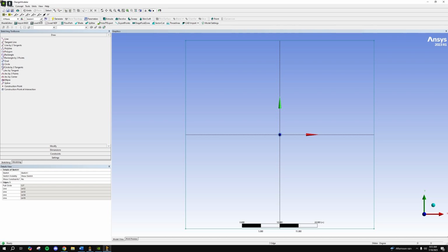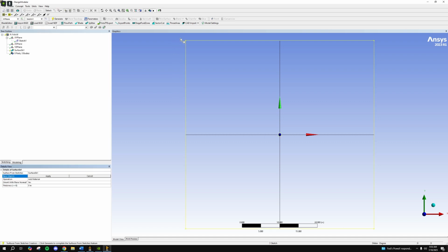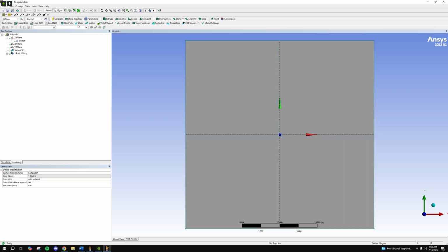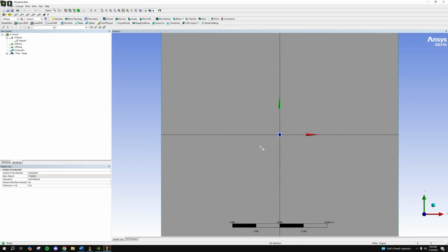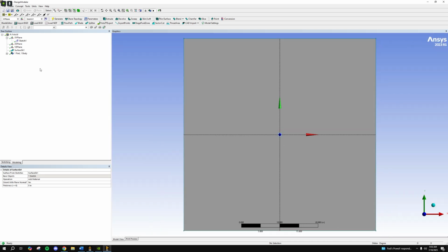We're first going to have to go through to a new sketch. Oh wait, no, sorry, concept, lines from sketch, surfaces from sketches. Click here and apply. And we're going to generate that surface. As you can see, the center is still open, which is exactly what we want to see. Then moving on from here, this is now done.